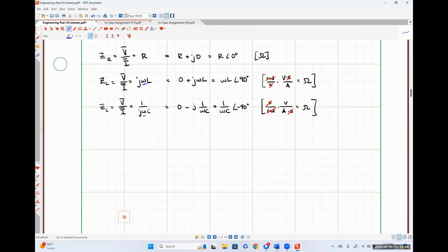No, no. So for a resistor, the magnitude shouldn't come from the left-hand side or the right-hand side of the rectangular form. We're just treating it as a complex number, right? Just to refresh your memory for something that we learned, I think it was late last week, and we talked about it very quickly. The magnitude of a complex number A is just the square root of the real part of complex number A squared plus the imaginary part of complex number A squared. That's right. I'm sorry about that. That just wasn't jogging my memory. No, no, not a problem at all.